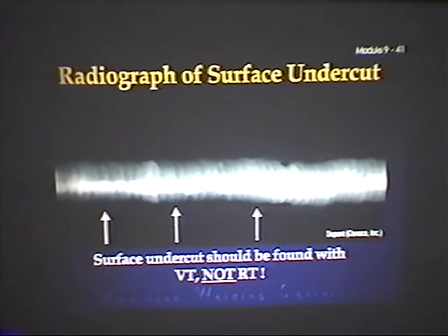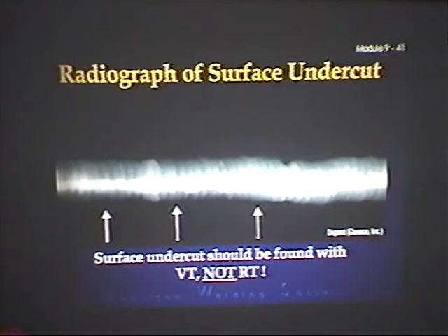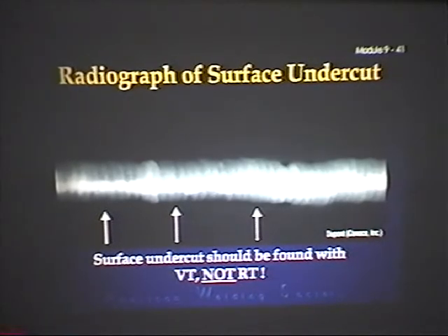Reading from your textbook then, undercutting. When the base metal along the edge of the weld is reduced from its original thickness, as shown in figure 13.3, the weld is said to be undercut. There are several reasons why undercutting occurs. Excessive current can cause the edge of the joint to melt, and the molten metal will wash into the weld, leaving a drain-like impression at the edges of the weld. This can occur in varying degrees, even with a normal arc length. Undercutting can occur if the electrode is not manipulated in such a manner as to supply an adequate amount of filler metal to the molten edge of the weld.